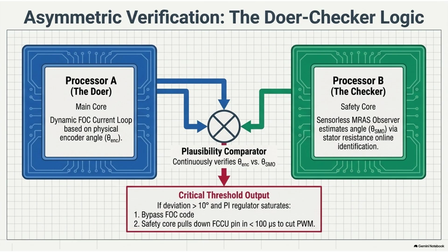The system executes a two-phase short circuit based on the last known rotor angle, which creates an asymmetrical magnetic field that allows some of the transient current shock to dissipate into the rotor's squirrel cage or magnets, absorbing the initial spike. Then, in Phase 2, it transitions into a full three-phase lower bridge short circuit. And this creates a symmetrical, steady braking torque that safely decelerates the motor and successfully clamps the DC bus voltage to under 720 volts, ensuring the inverter and the high-voltage battery actually survive the event.